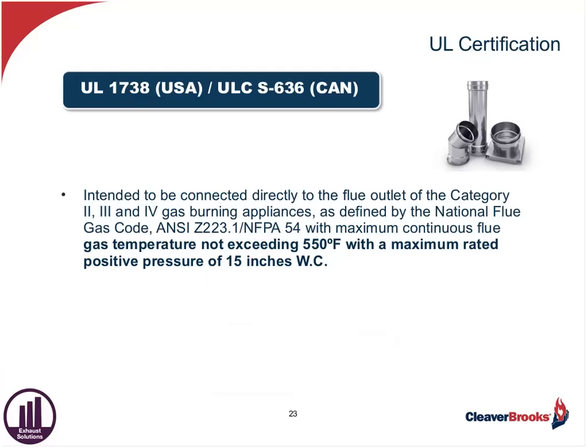Now, the other thing is certification. With these materials, it's highly recommended by the industry, not just Cleaver-Brooks, that the material be UL certified. With the certification in the States, it's UL 1738, and in Canada, it's ULC S636.